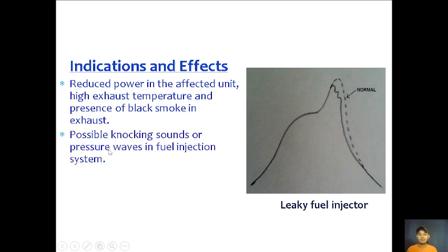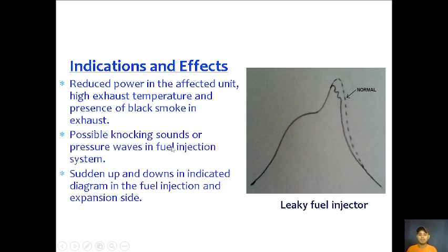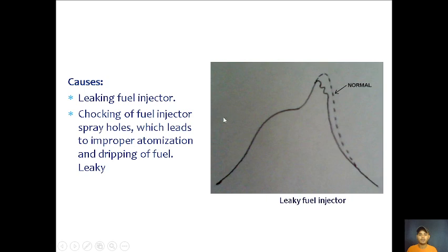Okay, reduced power in the affected unit, high exhaust temperature and presence of black smoke in exhaust, possible knocking sound or pressure waves in fuel injection system, sudden ups and downs in the indicated diagram in the fuel injection and expansion side. So after burning is due to incomplete combustion of fuel. Causes: leaking fuel injector, choking of fuel injector spray holes, which leads to improper atomization and dripping of fuel, or leaky. So that is for leaky fuel injector.